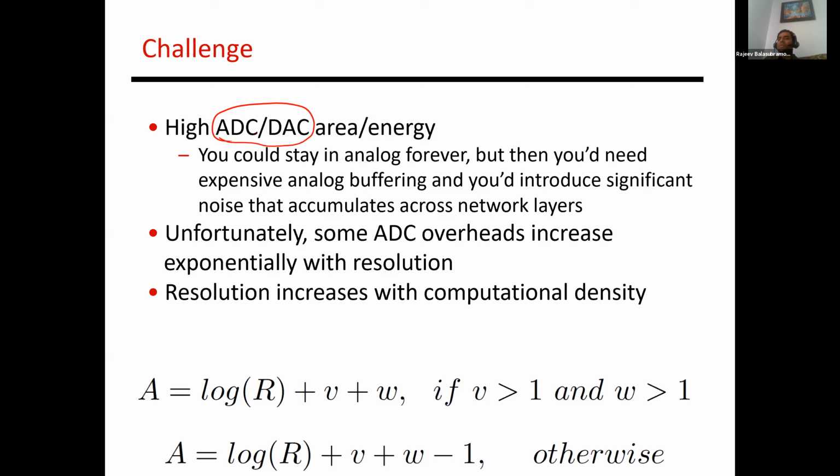So you're not actually doing multiplications and additions. That just happens naturally as part of Kirchhoff's law, right? And so, there's all this efficiency advantage that you get with the read out of a memristor. But then if you have to send all the signals through an ADC, then all of that benefit kind of goes away, right? And so that's the main drawback that we have to overcome.